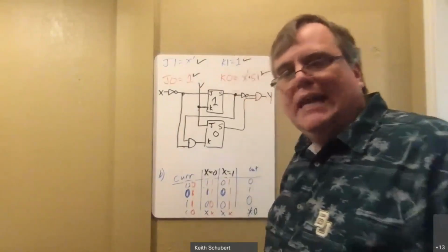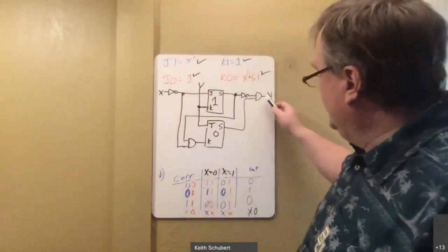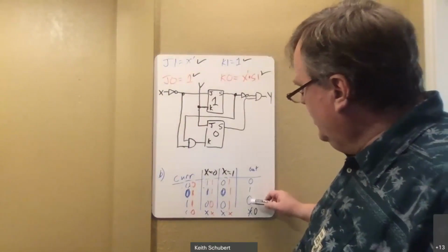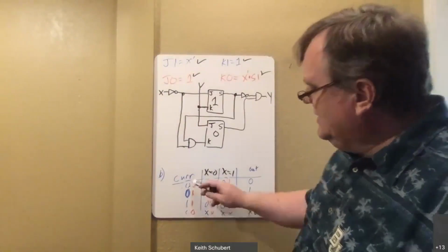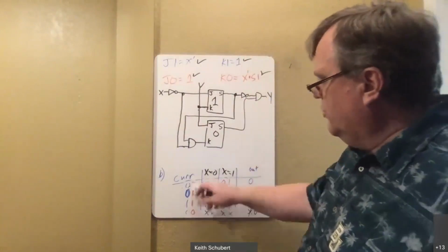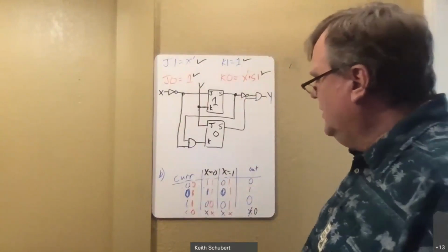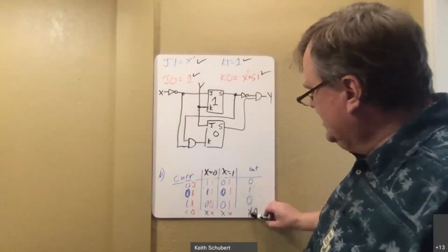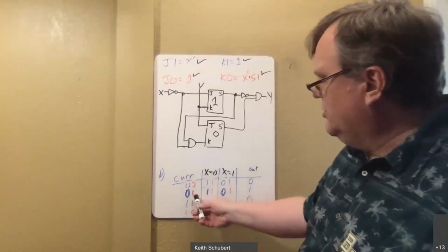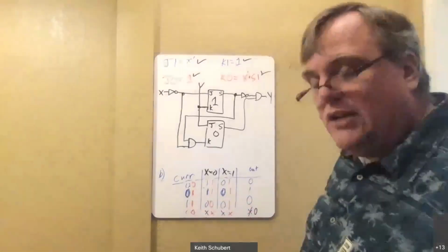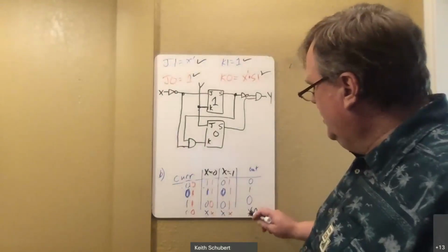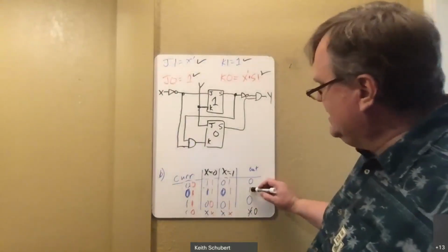So the final AND gate here, this is the output. I looked at my output and I had 0, 1, 0, X. Since this is already put into a gray code ordering, I could pick this to be a 1 for the output if both of these are on, which means I need 0, 1, and 1, 0. So I could do an XOR gate. Or I could do what I did, which is I just marked that off, put that as 0, in which case this is the only 1.